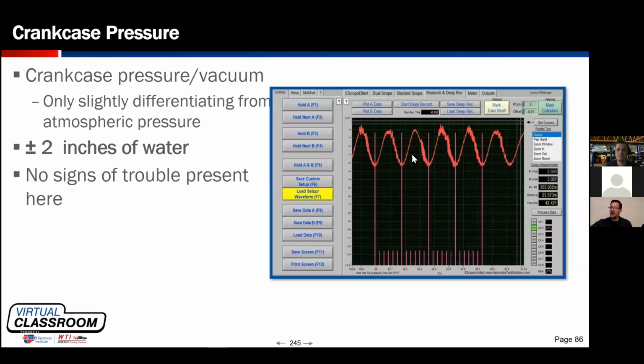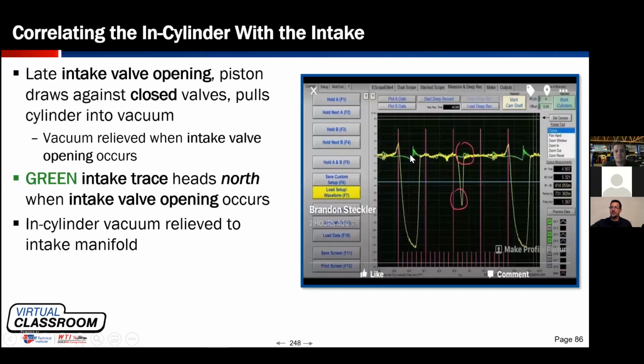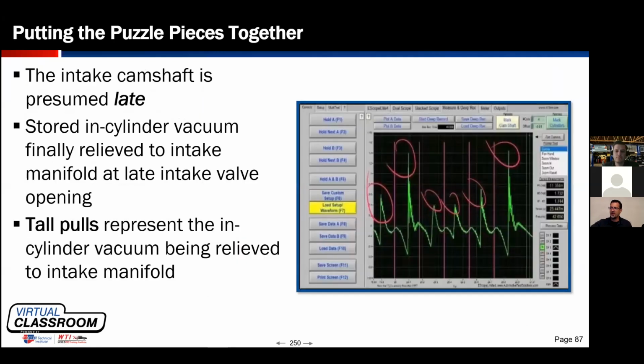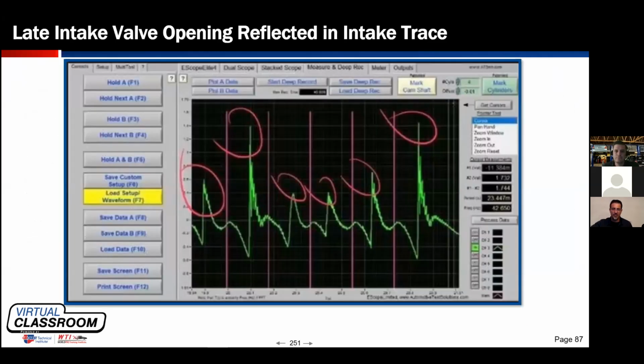So, putting the puzzle pieces together, I put the car up in the air, and I saw oil. I wanted to know where that oil was coming from. I thought I had a hole in the block. I saw the oil was coming from between the transmission and the engine, in the bell housing. I got a borescope up there, and I saw that the rear main crankshaft seal was pushed out of its bore. It was displaced. I said, how the heck could that happen?